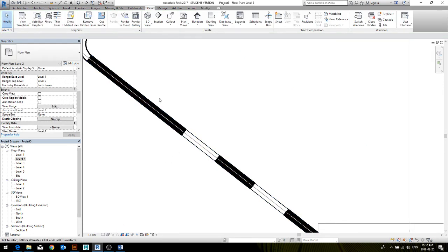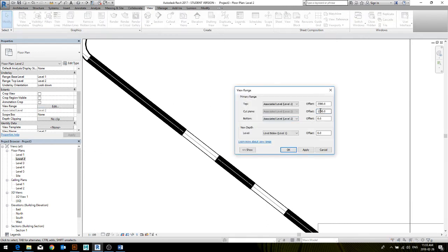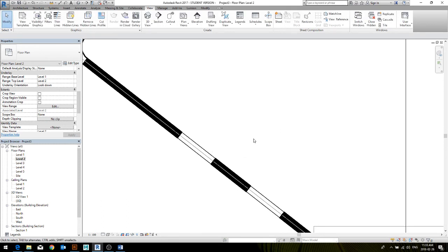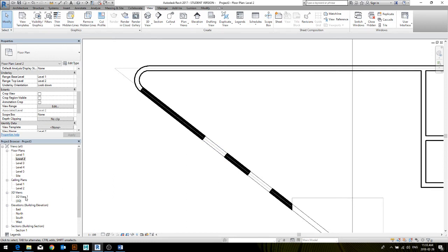Okay, now these are cut and that is open only because that's where it's cutting the plan for me. So if I change that cut elevation, it will cut it from a different location, and then now you can see how that is changing. I'm pretty sure you guys are familiar with how the plans are drawn. You have a 3D model that is cut from a certain height, and then depending on where it's cutting, you can see your doors, windows from where it's cut. And if you change that, maybe some properties are changed. That's where you can control it.